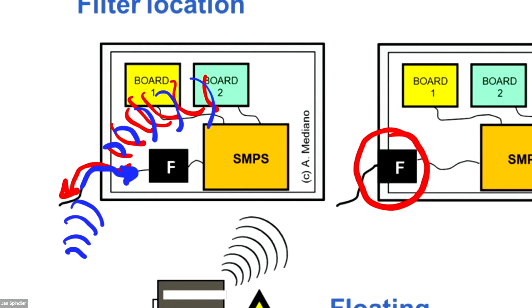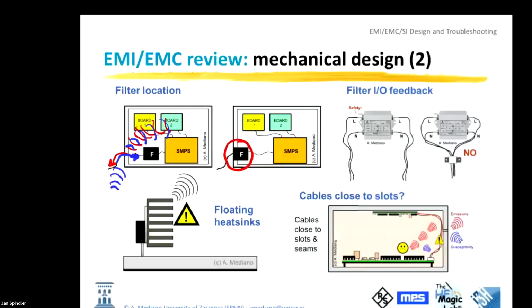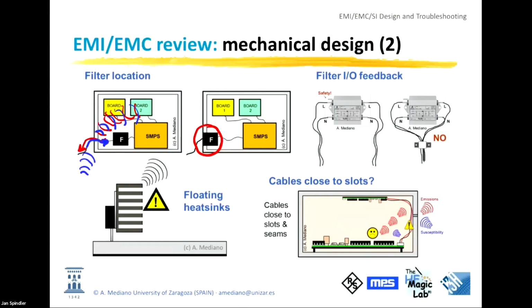When you are designing the mechanical structure, you say cables go in this position, so this area is for the filter. And better if the filter is shielded. This is magical, okay? You need to check things like this, not only in cables, you can check in the PCB. The input and output of filters must never go one close to the other. You will create feedback, check that.